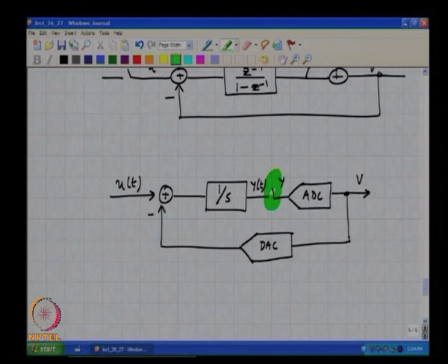So, one question is, do I really need to put an anti-alias filter at all? Okay. So, in other words, if this input signal, which is anyway being sampled at the output of the loop filter inside, consists of high frequency components along with the desired low frequency component, clearly the high frequency component cannot be represented as samples of u of t with the rectangular pulse shape, right.